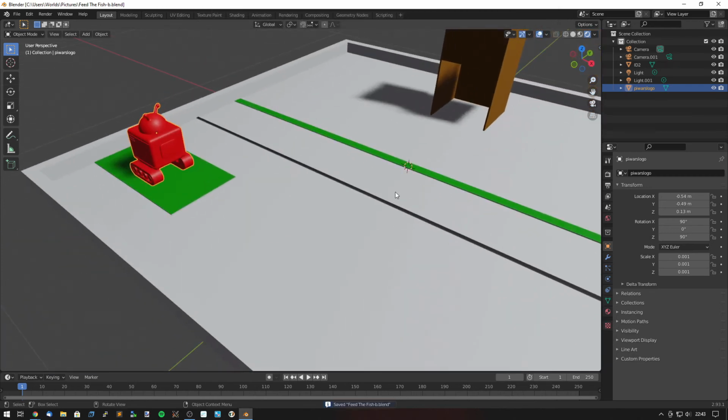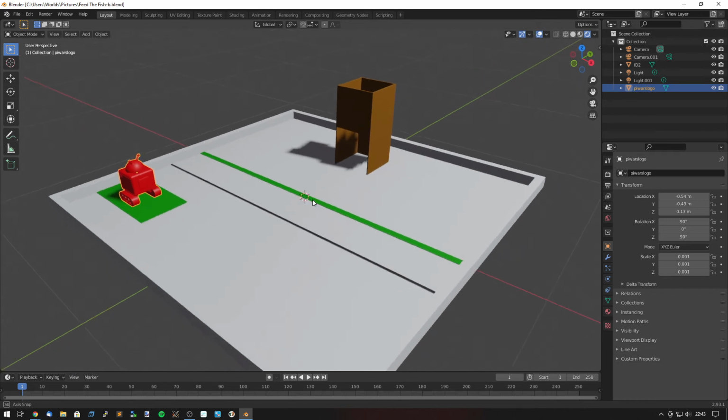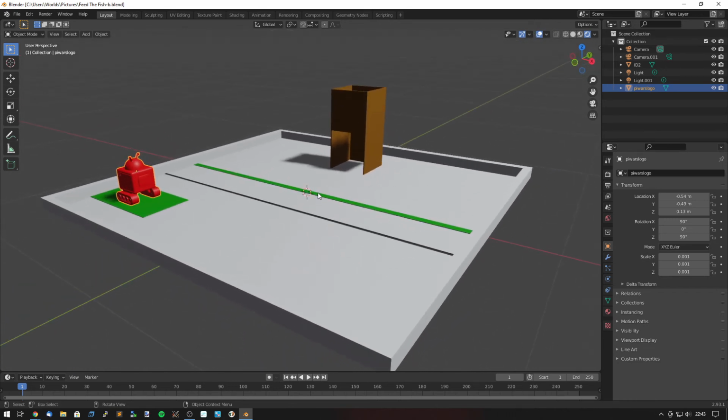I have found out Blender does occasionally crash. It is not the most stable of programs in my experience. So just make sure you save your file before you do certain things like rendering or animations. Mainly rendering, I think, causes it to crash out sometimes, but just in case, you may as well do regular saves. So I've got everything as I need it.